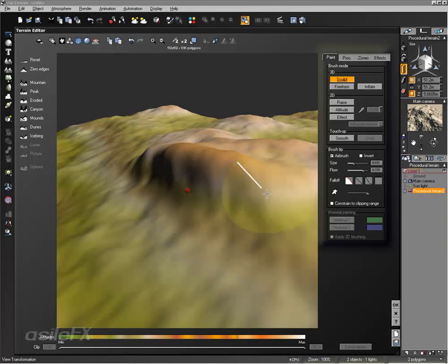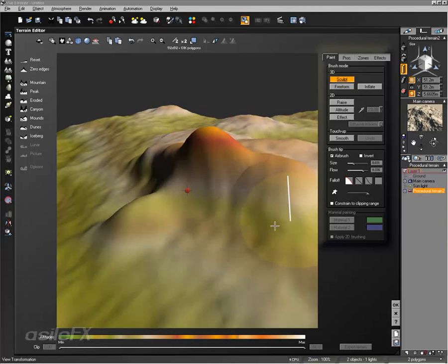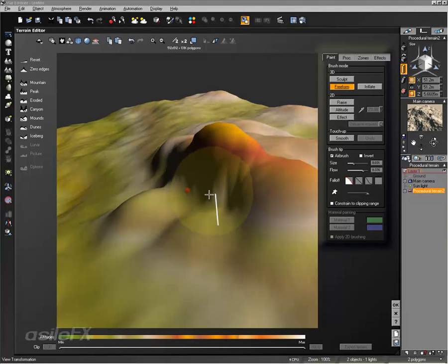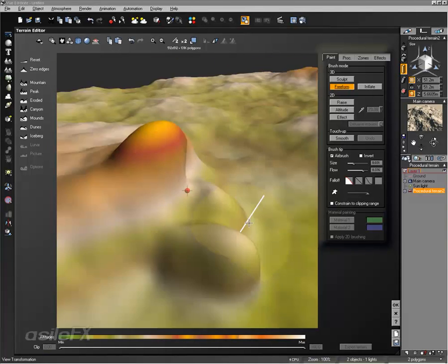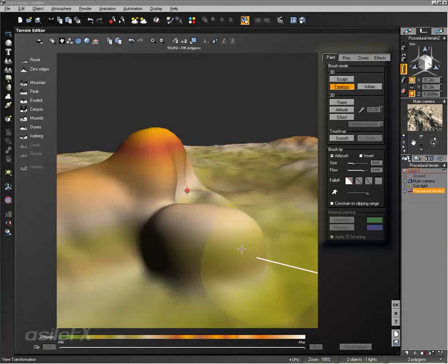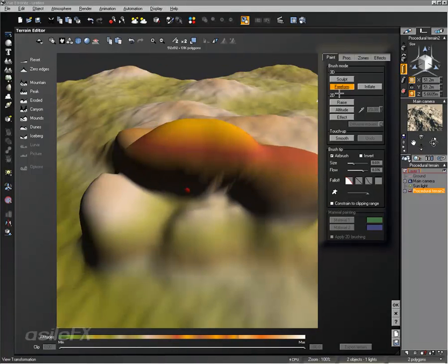And when using the Sculpt mode, it becomes fixed depending on the first click. So now we're pointing pretty much straight up, and as I continue to paint, it's going to also continue to point in the direction of the initial normal selection. The freeform mode will conform to the normal and continually change. So that is the main difference between sculpt and freeform.